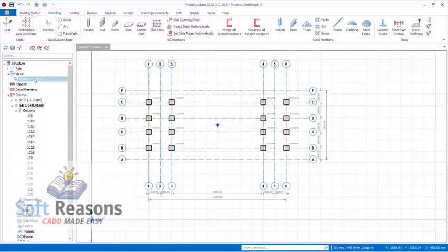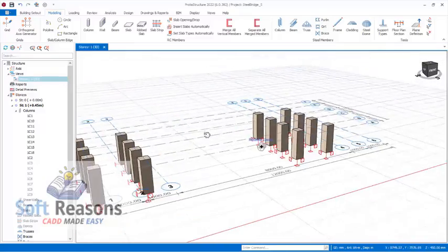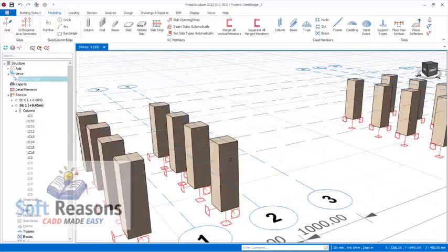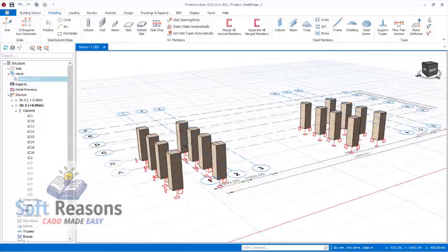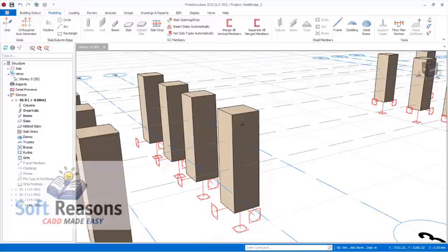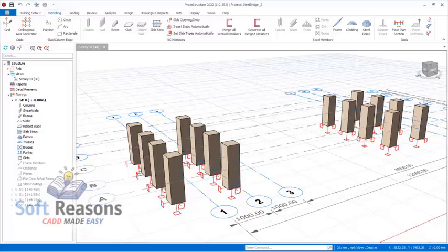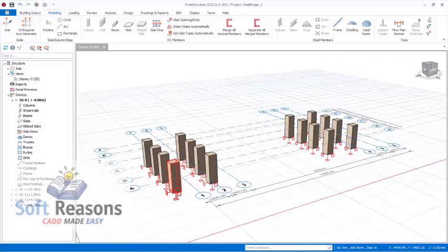reinforced concrete member, but by then let us navigate to the 3D so you can now see what we are having here. Alright, so we have this. If you double click now on story 0, you can see this. So here is the 450, from the top of this pedestal to where the grid line is, and then from the grid line to the foundation depth, you have 1.1 meters. Okay, so we make progress.